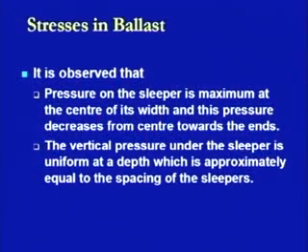So, if we go up to that particular depth, then we have to find out what is the total amount of stress remaining at that level, and whether those stresses are lesser than the bearing capacity of the subgrade soil or the formation which is provided at the bottom. If it is so, then it is fine. If it is not so, then the depth of the ballast cushion is to be increased.